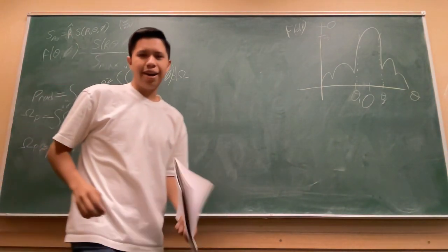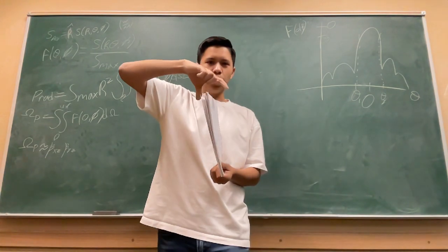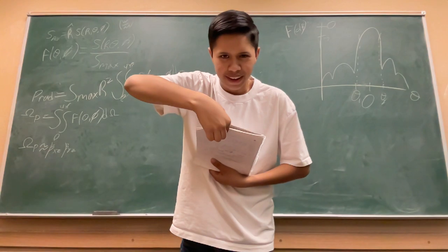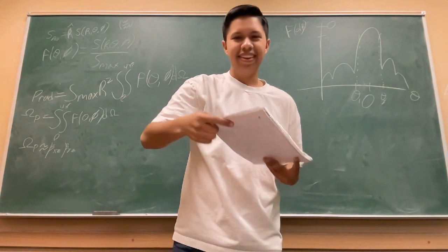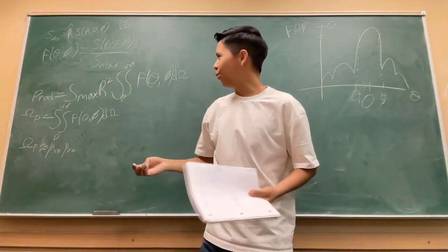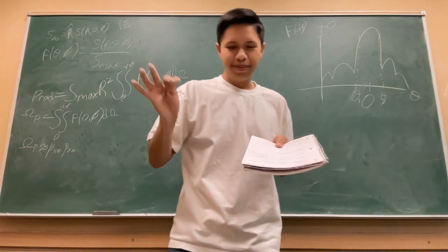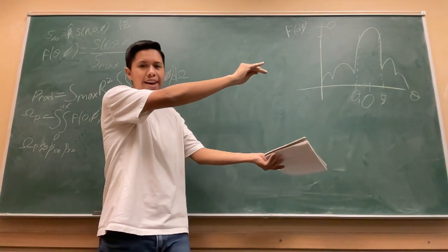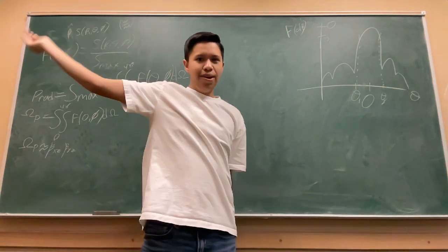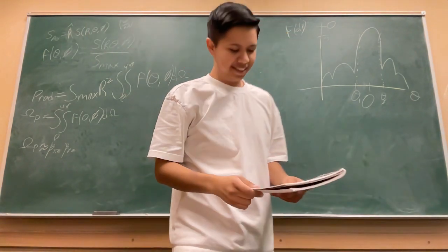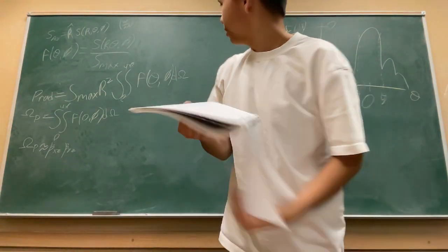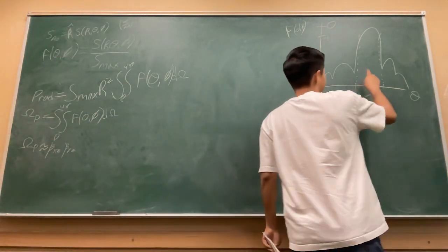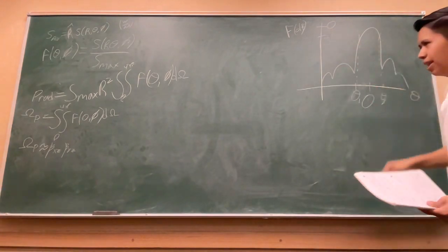And when we approximate a pattern solid angle, we're going to get a cone. So if we have the width of the cone in one direction and the width of the cone in another direction, we can just revolve it, and then we're left with a cone showing the direction that our antenna is radiating in. If it's a cone, then it's radiating one way, and if it's a whole sphere, we can see how wide the radiation of our antenna is. Those beam widths come from the half power beam width of our plot.